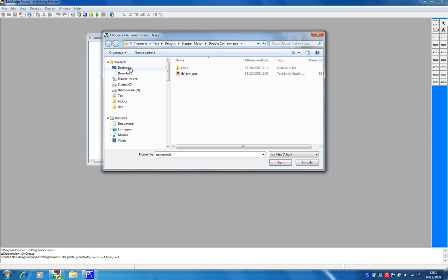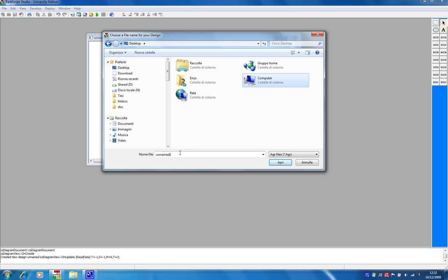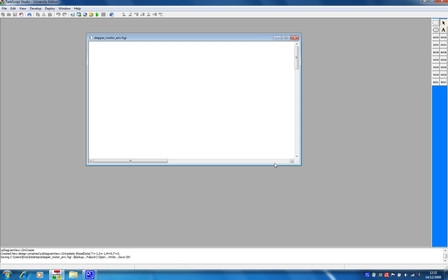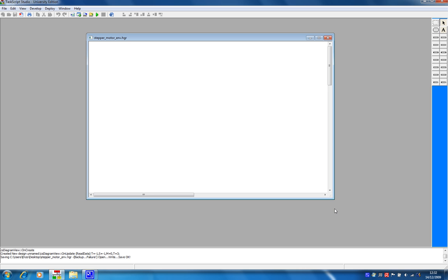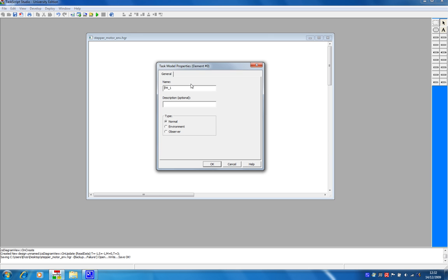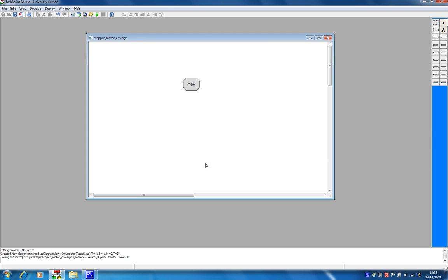This kind of motor has 4 coils which, when energized in the correct sequence, cause the permanent magnet attached to the shaft to rotate. There are 2 basic step sequences. After step 4, the sequence is repeated from step 1 again. The kind of stepper motor we are going to model is called two-coil excitation, where each successive pair of adjacent coils is energized in turn.